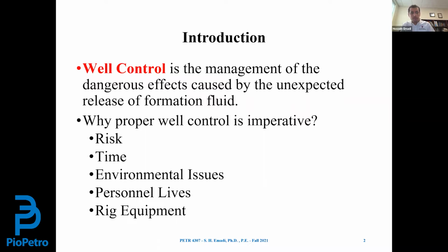There is a difference between a kick and a blowout. Obviously, the kick is when formation fluid starts entering the wellbore, and we can have control over the situation, and we can manage the formation fluid which is entering the wellbore. However, if for any reason we lose the control over the operation and formation fluid reaches the surface in an uncontrolled manner, then this becomes a blowout. Obviously, a blowout is much more costly and much more dangerous than a kick.